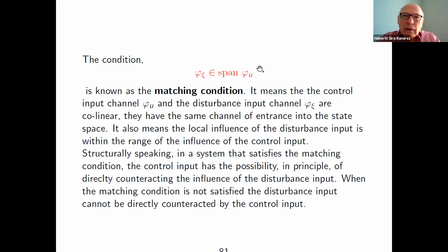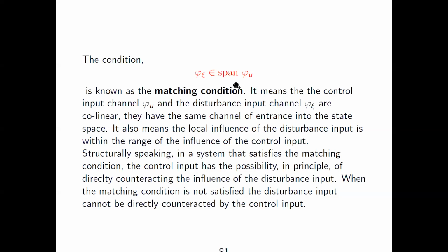Well, in the first case, the disturbances enter into the realm of the linearizable variable. So whatever transformation you're trying to apply to linearize the system is going to fail. It's going to fail because those coordinates depend on the disturbance, and you don't know the disturbance.